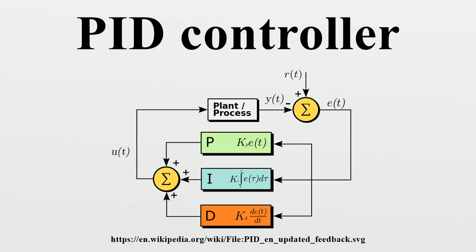Overview of methods. There are several methods for tuning a PID loop. The most effective methods generally involve the development of some form of process model, then choosing P, I, and D based on the dynamic model parameters. Manual tuning methods can be relatively time-consuming, particularly for systems with long loop times.